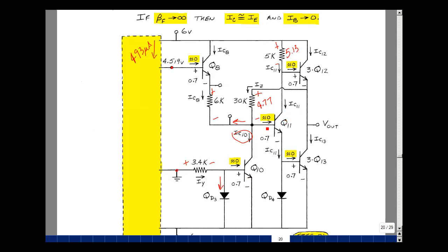For transistor 11, we solved for the current here and found that it was 20.52 microamps. The current entering is I sub Z, which was equal to 159 microamps, so pretty small. And of course the current coming in here was I sub C8, which is 1.4 milliamps. So some very large currents compared to 20.52 microamps, so neglecting that seems also reasonable.